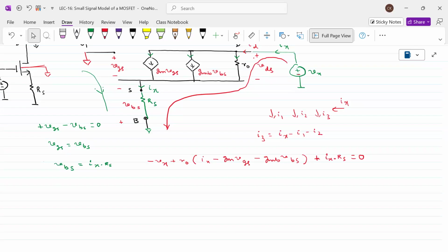So here, can you see the VBS? What is the VBS here? Observe carefully. VBS is actually not plus Vx. It is coming from the source terminal point of view. This is the plus here, and this is the negative here. That is the drop across that one. That means the current enters into the negative terminal of the source. You can observe that the current is coming from the negative terminal of the source. Negative potential. That's the reason why this should be negative.